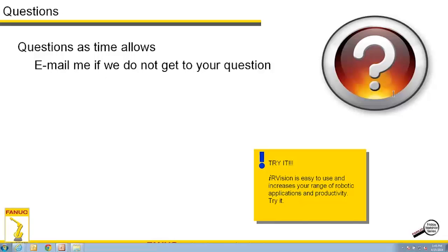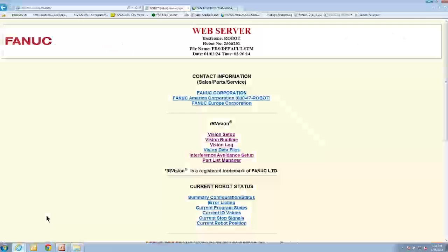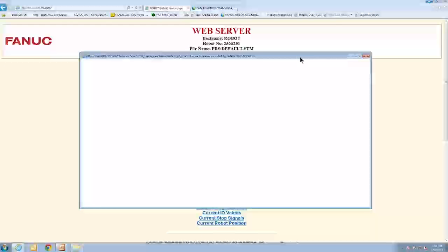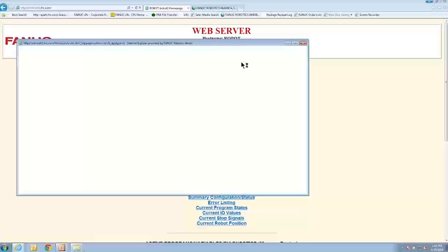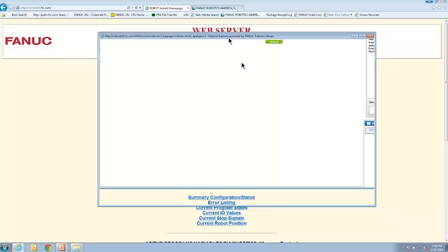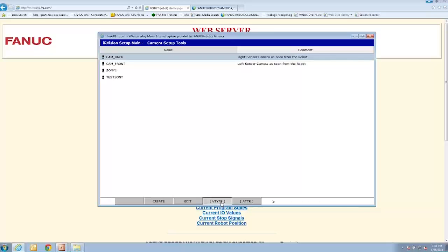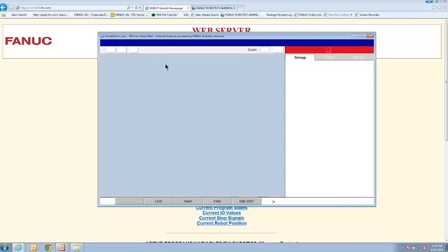And another question that would come up is in terms of the pixel error limit. Some people were asking previously about that. When is it too high? Hang on one second. Pull this up. So I'll just go ahead and navigate. We'll just look at that. I could talk about that for a few minutes. But basically, when you calibrate the vision system, it'll come up with a magnification of millimeters per pixel. So if I go ahead and go to my calibration, create Sony Cal, for instance.